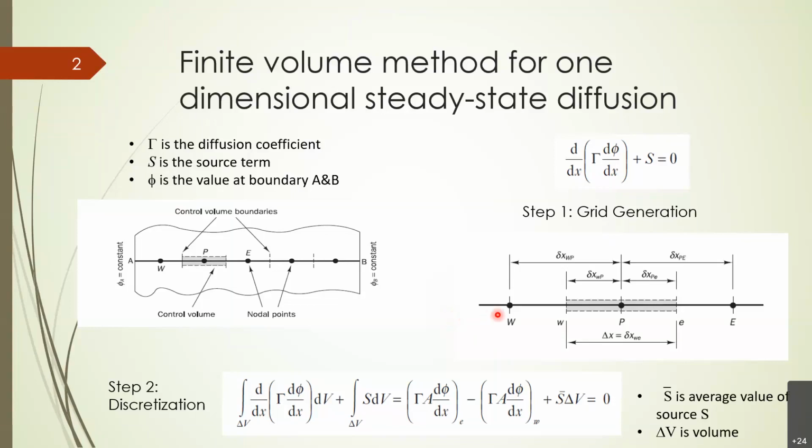Now suddenly we want to introduce some kind of turbulence in the middle of the channel. The introduction of the turbulence can be done by using this part, the source term part, S. Similar to Navier-Stokes as well as the control volume equations that we have over here, if you want to introduce anything inside the moving fluid, for example, when we are dealing with Navier-Stokes, we have to do it using the source term.